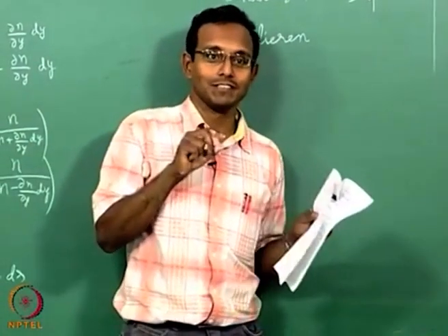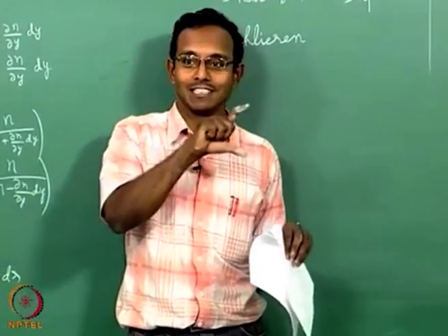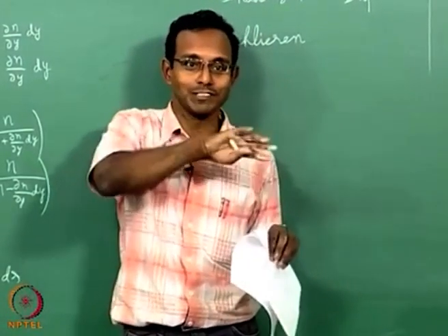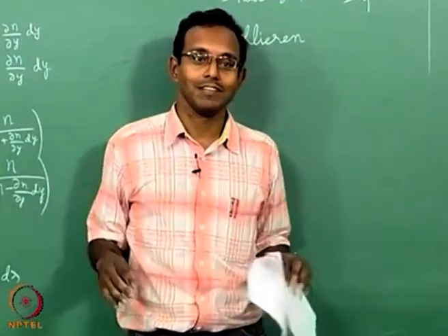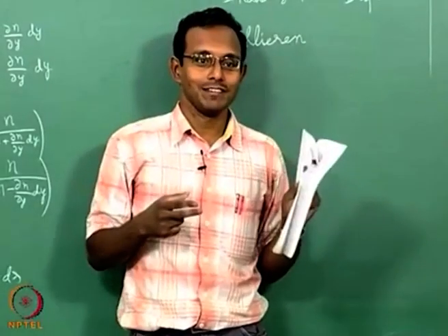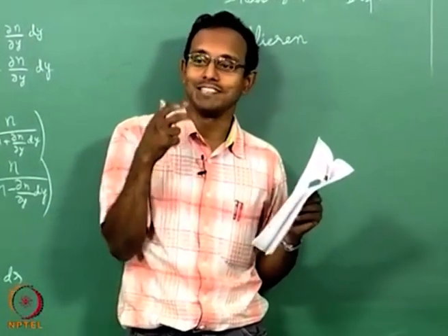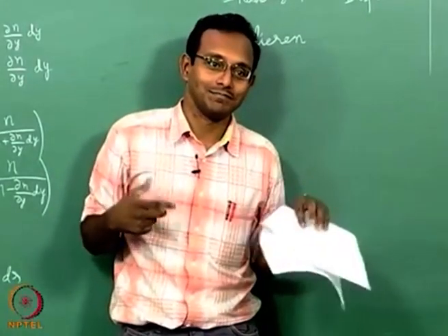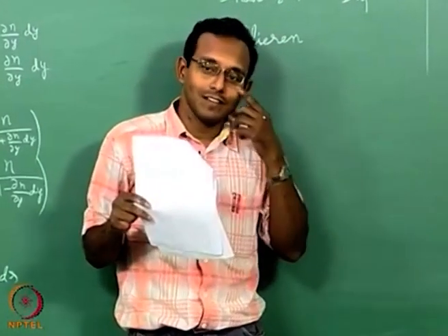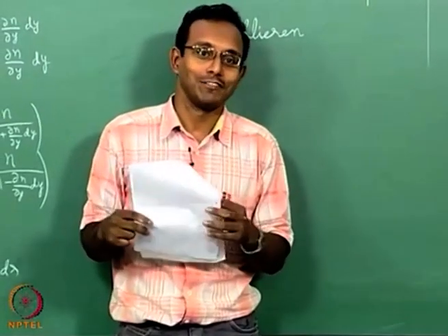Because each region has different thicknesses, it is like a glass slab with varying thickness, forming something like a lens. Because of that, if you look at a parallel beam of light coming from somewhere, the lens effect will focus the light to some point, so I will see something different on the other side. This particular phenomenon was labeled as the Schlieren effect.